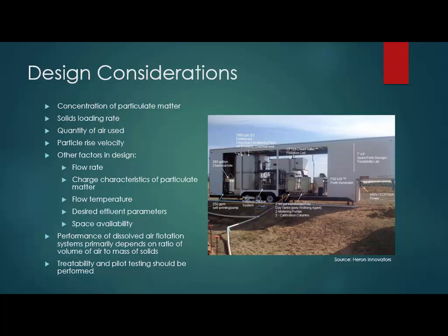We also need to get an understanding of how quickly the particles will rise to the surface when they are attached to the bubbles. Other factors that may come in or need to be taken into account are the flow rate coming in. You need to know how large of a tank you need. You need to understand the charge characteristics of the particulate matter. Are the bubbles going to attract what you're trying to remove?